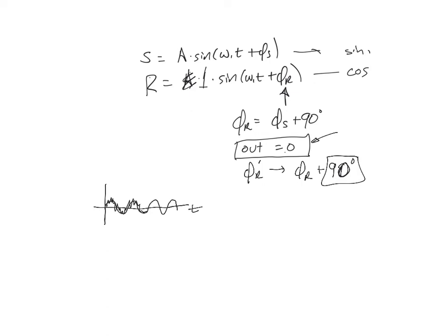And that noise, if I took the Fourier transform of that, took the power spectral density of this signal with the sine wave on top of it, remember the noise has the white noise and the 1 over f. And the signal now I've put out here, so there's actually a line now in my power spectral density due to the signal, right? The time constant sets how much noise I'm going to have left over in my output.